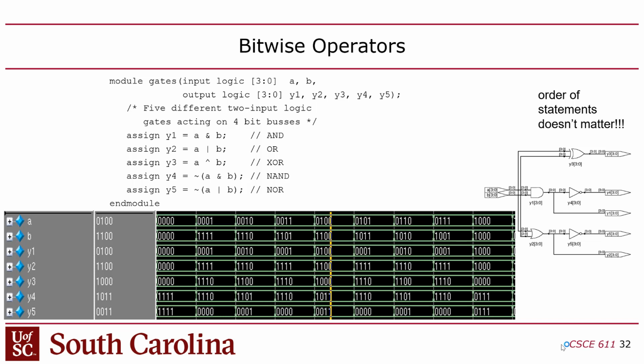But here's the catch. Verilog has something that I never can get used to. After years and years of writing Verilog, I can never get used to this. When you declare a multi-bit signal in Verilog, they do the most unexplainable thing. Well, there's two things they do, actually. The first thing is, instead of just saying 4 for a 4-bit signal, you say 3:0. Means 3 down to 0. 3, 2, 1, 0, 4. Why can't you just say 4? Why do you have to say 3 down to 0?